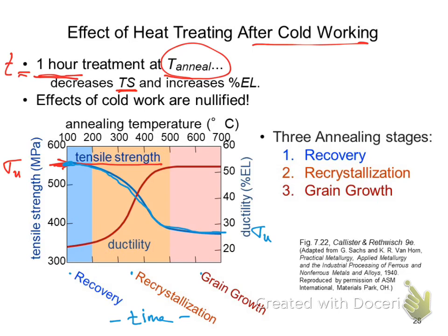Now, in the opposite direction, we have ductility as the other property we're going to look at. The ductility starts out low, and at the end, we end up with a very high ductility. Remember that we're talking about percent elongation? Go back and look at that definition if you need to. The effect of the cold working created high tensile strength, and it created maybe low ductility, because those members with that high tensile strength become very non-ductile and brittle, right? It's very brittle here.